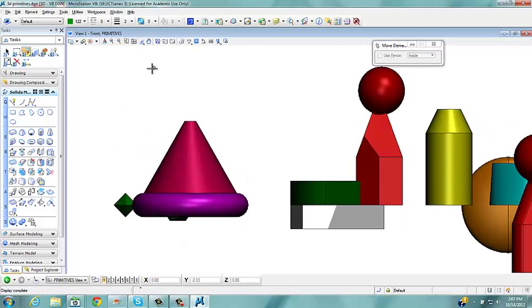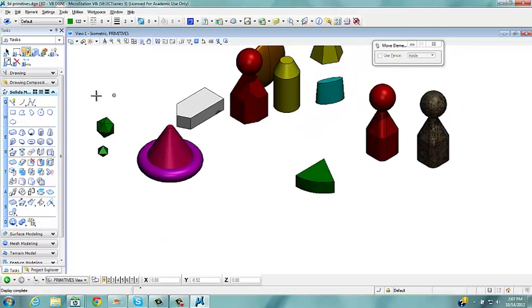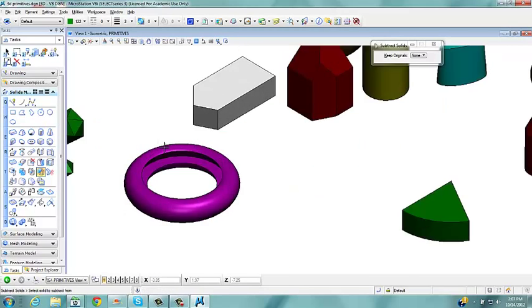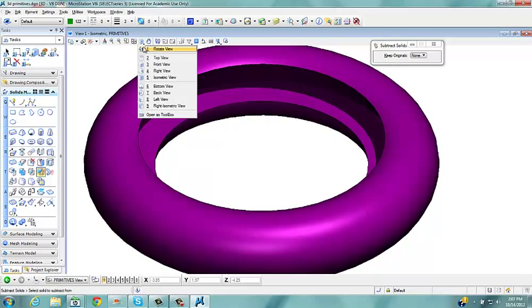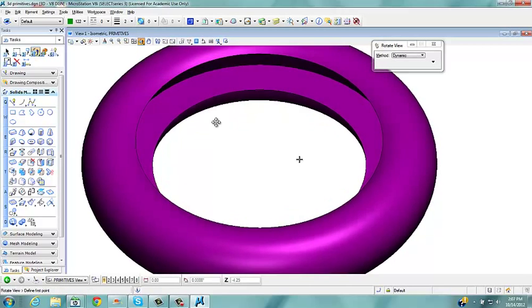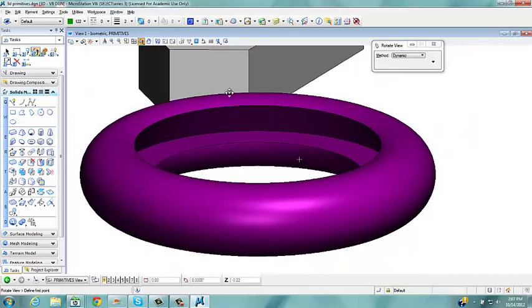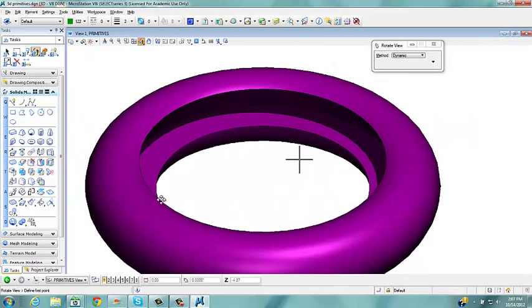Bring it up to a front view, and we'll pull this down. I'm not sure what this is going to create, but we go to our isometric now and say I want to take the difference, and I don't want to keep any of the originals, between this shape and this cone. You'll see what it does is it gives me this kind of hollowed out section of tube that gives me a pretty spectacular looking object that has these cuts in it. So doing something mechanical is pretty easy.